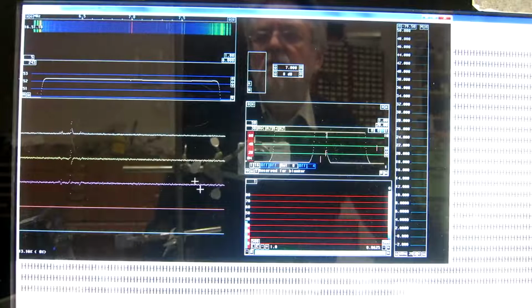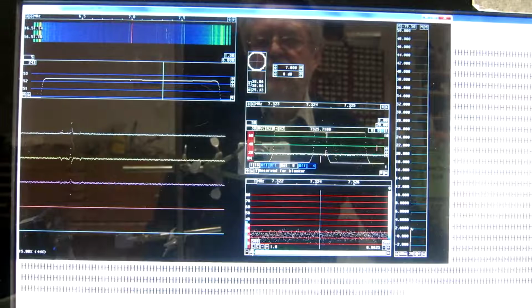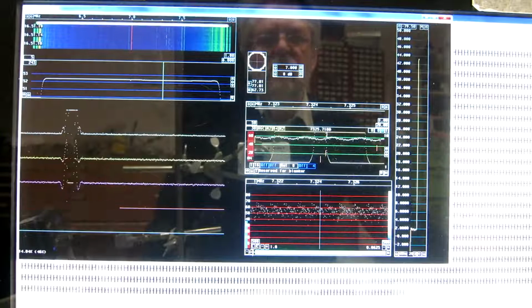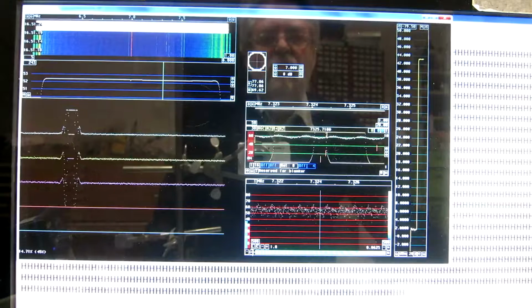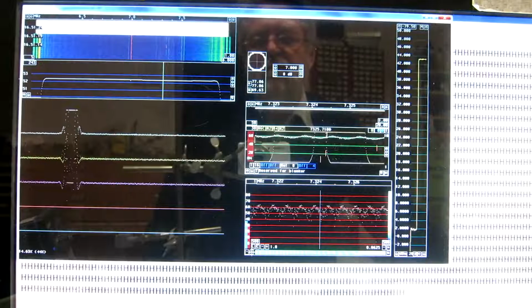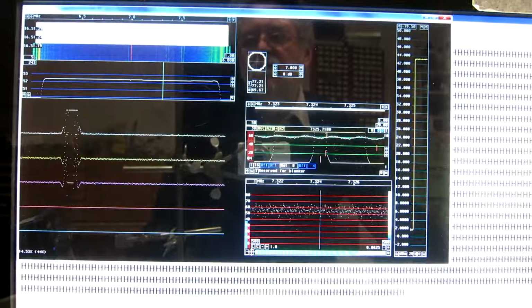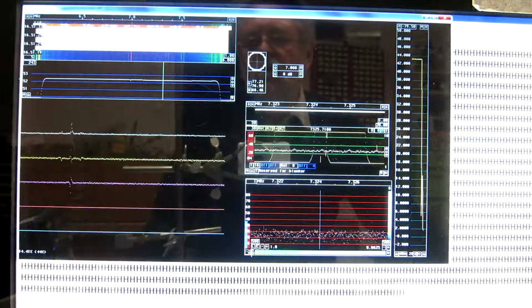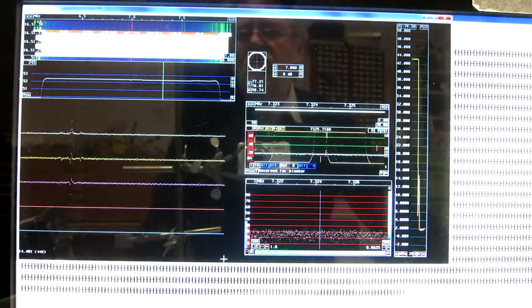And select the signal here and disable the blanker, and it's over 40 decibels at the pulse repetition of 700 Hertz. So now I go for the second stage of the calibration.